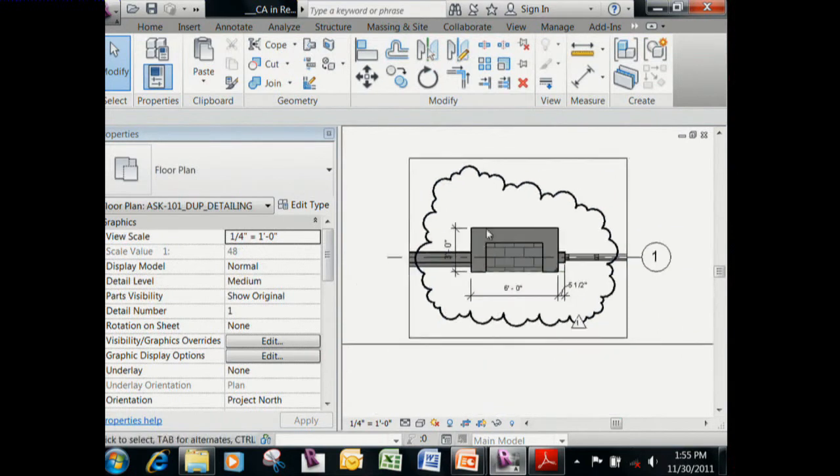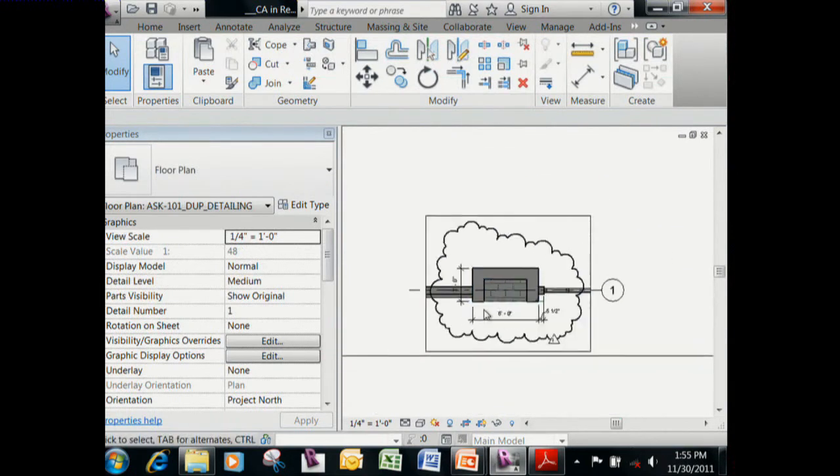So you have to have a rigorous process in place where there's a sequence of events that you always follow: make the changes you're going to make, do all the clouding, and then you place the view onto the sketch sheet. And the only thing that you're doing in the sketch sheet is changing the format, really. You want to try and avoid doing any changes to annotation there.